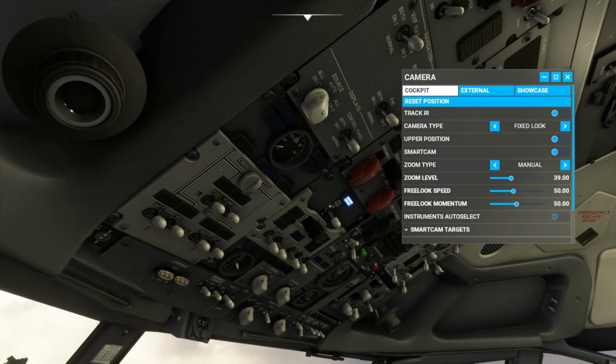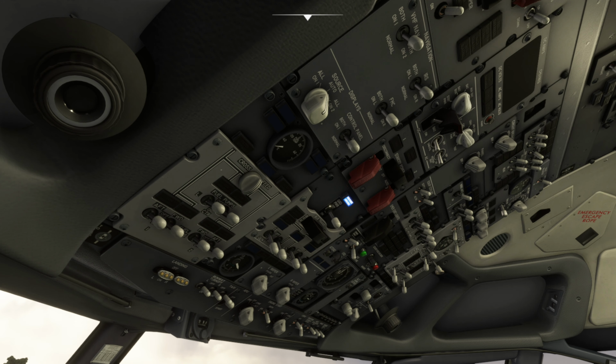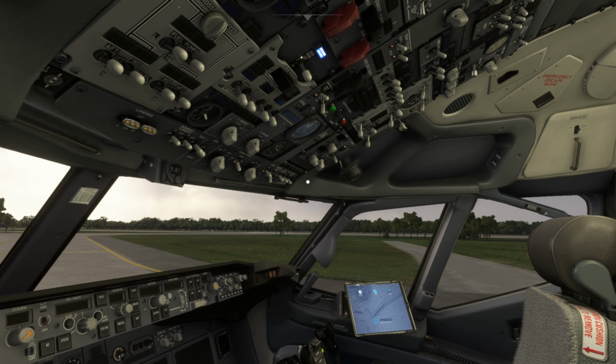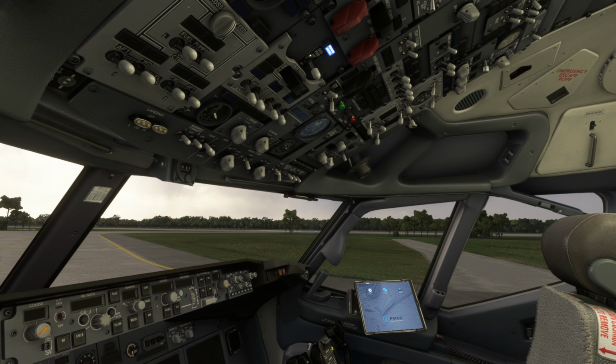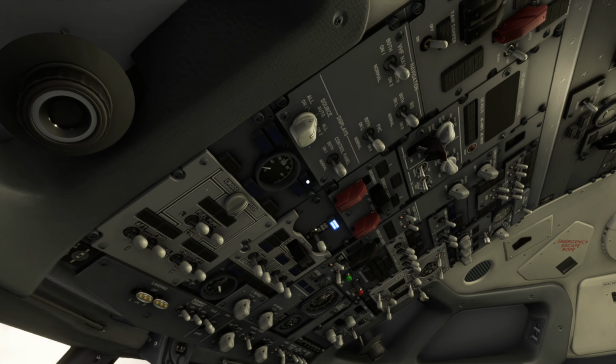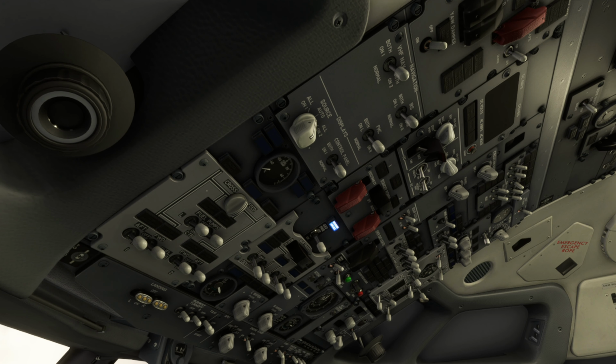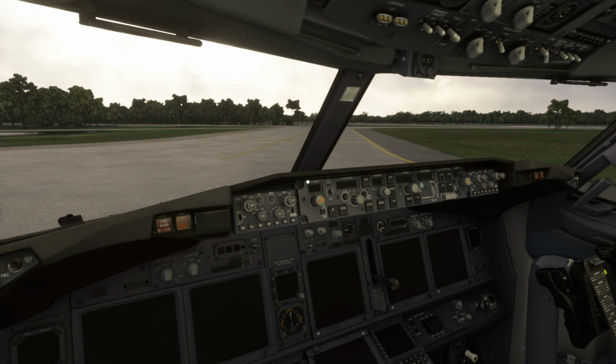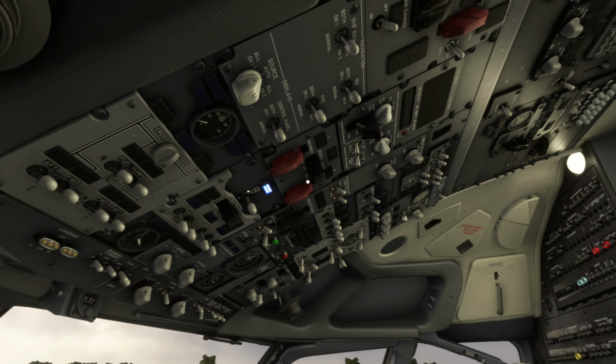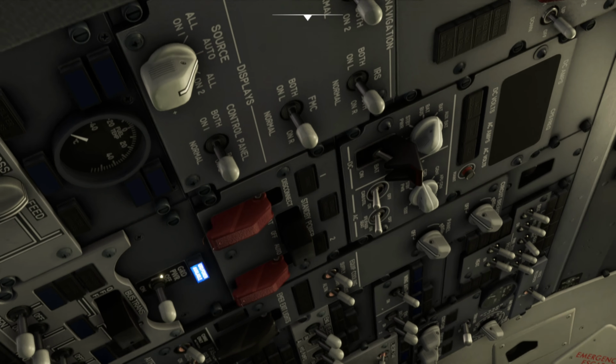However, it's generating a very negligible amount of thrust in terms of flight control, but it's a jet engine running off the same fuel system as the rest of the airplane in terms of the 2 main engines used for thrust generation in flight. However, that engine is very important for generating hydraulic pressure as well as electrical power, as we will find out.